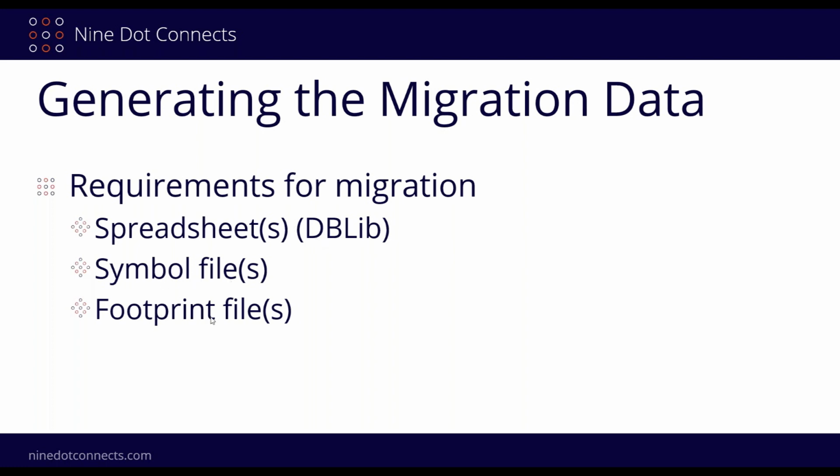Symbol files, so your symbol files use symbol footprints. The fact is, and let's just make it clear, all three of these have to be ready to go and they're already done. You don't want to do any post cleanup later on, because you start doing that and you're going to start bloating your database. Right? So let's say you had a resistor and, for now I'll just throw this resistor in there, and then later on I want to clean that up.